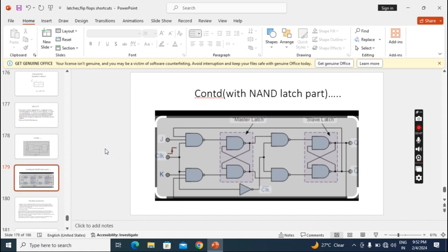Okay, so this master slave flip-flop is called a pulse triggered flip-flop, because during positive the master is working, during negative the slave is working. Together in the total pulse, the whole circuit is working. So the final output becomes the slave output and the input becomes the master input. Okay, right.